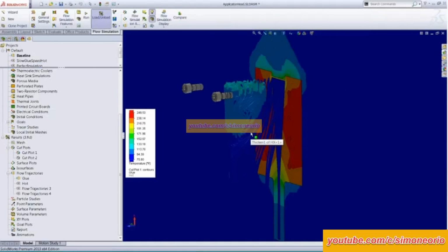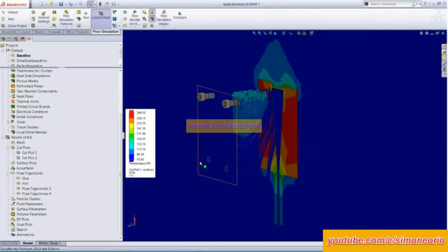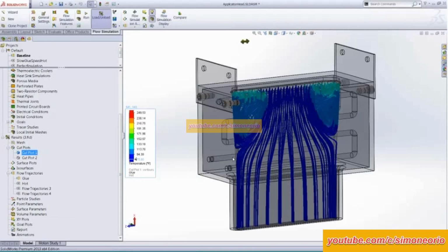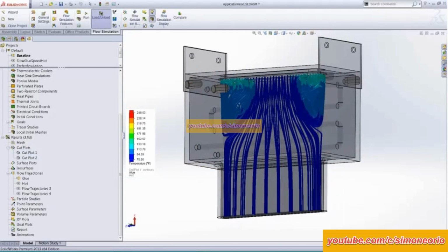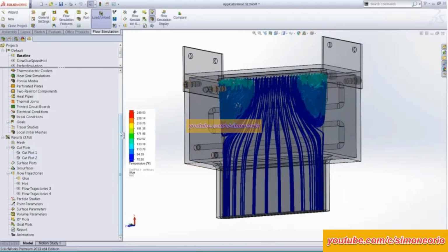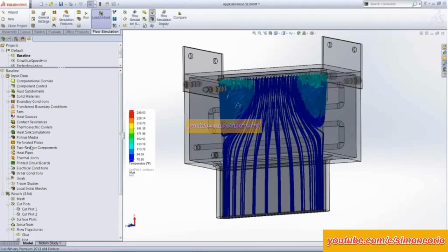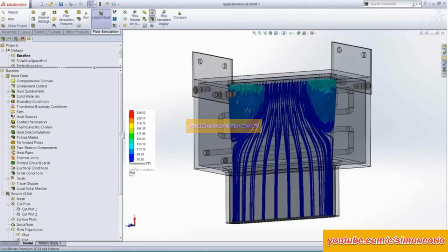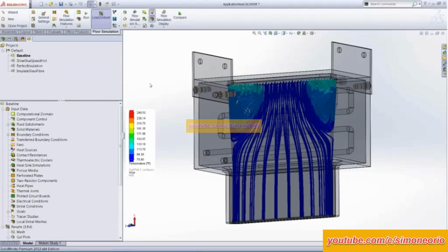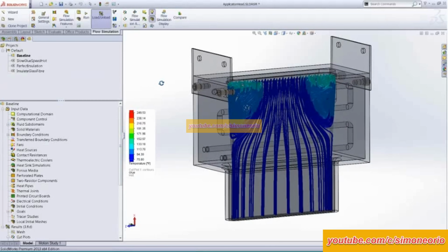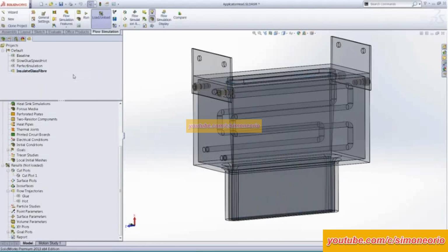So what are my other options, or what parameters do I have here to create a more consistent temperature across my adhesive? I can change the flow rates of my incoming hot water. I can adjust the flow rate of my adhesive to some extent. But what I found was the key here was decreasing the amount of heat lost to the atmosphere. So I have another version of this model where I insulated the outside of the model.